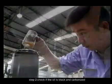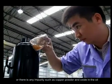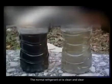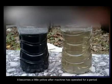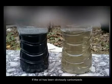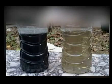Step 2. Check if the oil is black and carbonized, or if there is any impurity such as copper powder and oxide in the oil. The normal refrigerant oil is clear and clean. It becomes a little yellow after the machine has run for a period, but it should remain clear. If the oil has obviously carbonized, it is forbidden to change only the compressor.